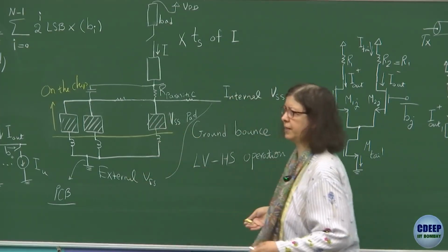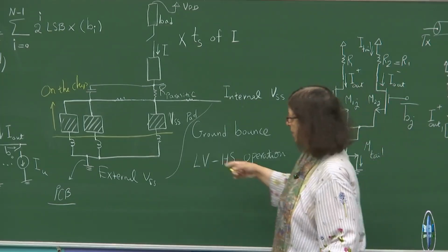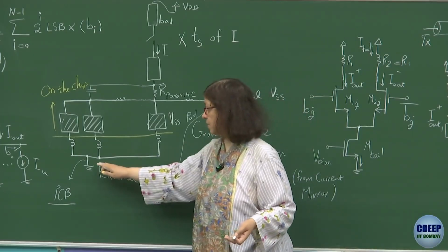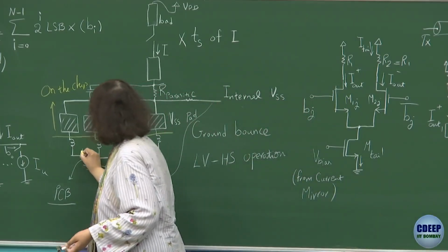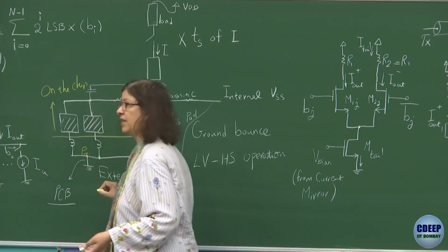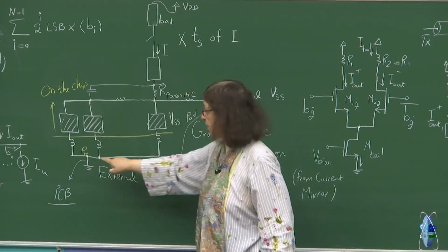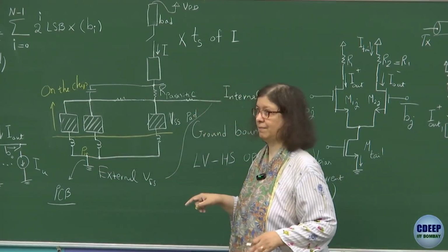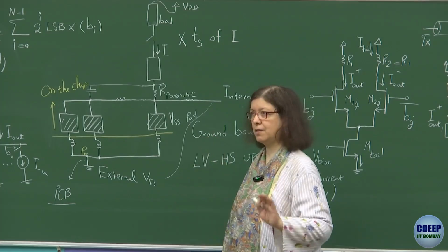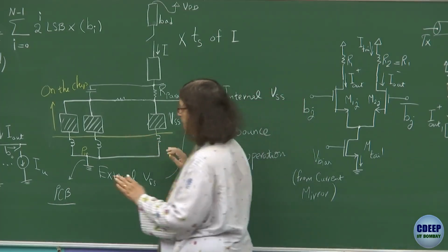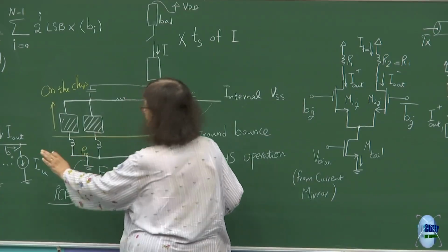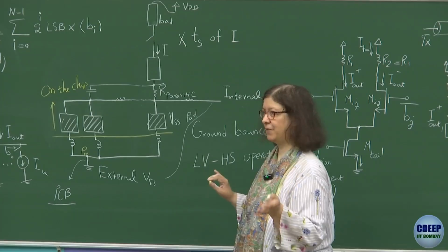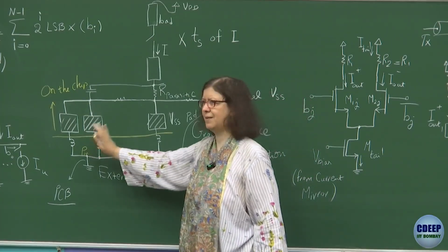There are different techniques for that. So this is that interface, that method of packaging. It connects to the outside. This is a pin, what we call the pin on the IC package. The pin of the IC package is not directly the pad. There are technologies that have that, but they are expensive. If that is the case, that's the best case. Even that contact may still have some inductive effect when we move to high speed. Therefore, we put this parasitic inductor here.